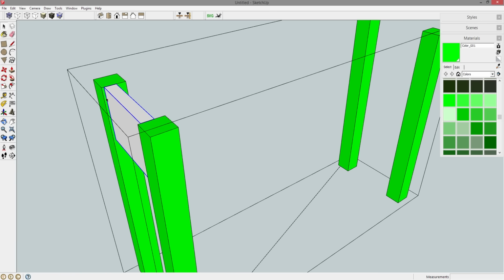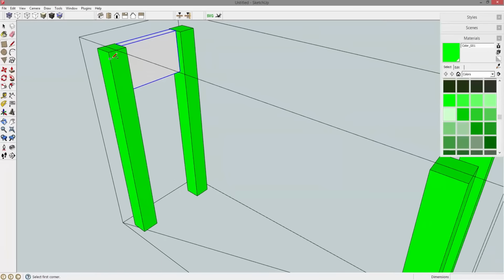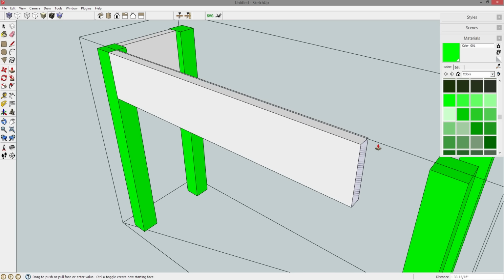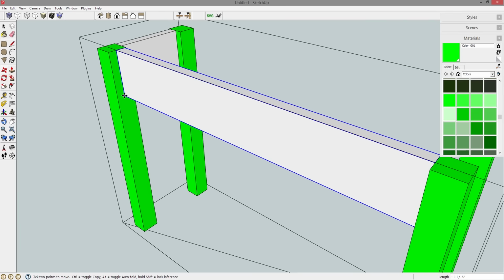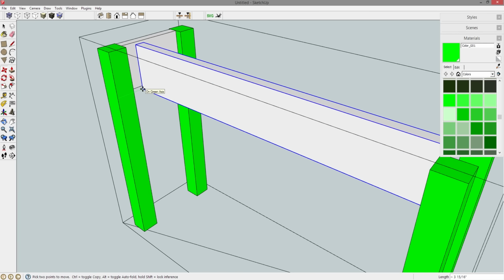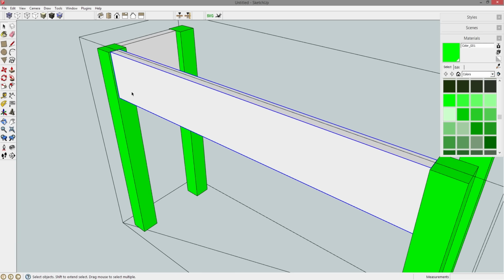from the legs. Same thing over here real quick, R for rectangle. Let's draw this one, and 6, 1.25, enter, P for push pull, and pull it to this leg. Spacebar, triple click, G for component, enter, M for move, and let's push it along the green axis into the project 0.25 inches, enter.